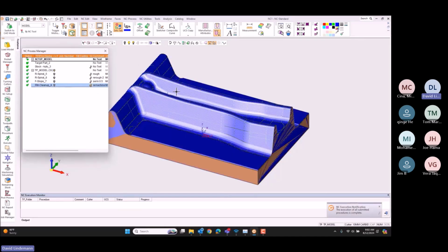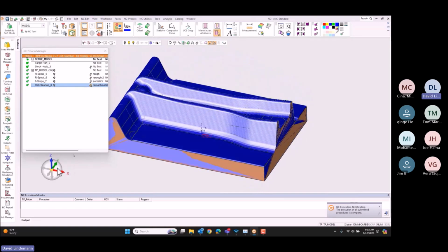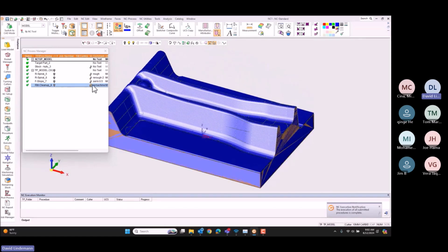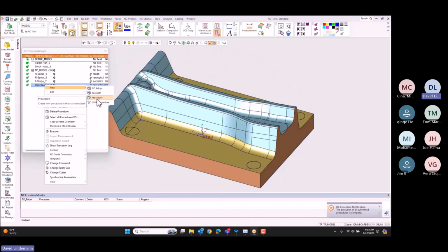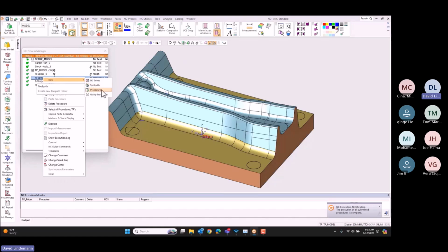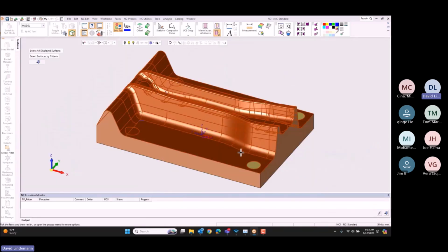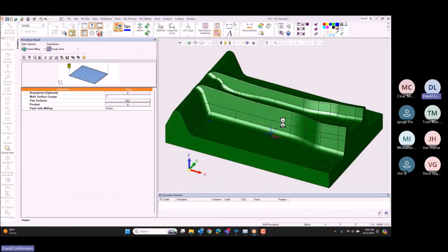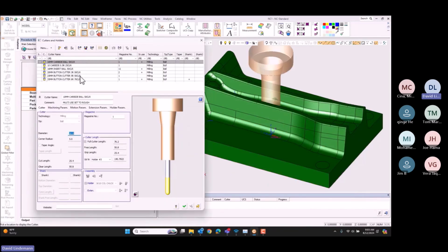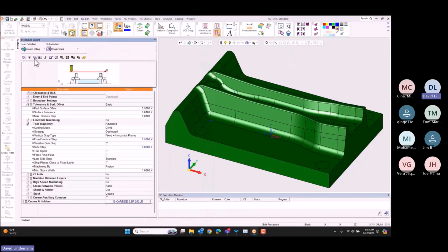And there you can see that nice cutter just targeting the corner where there's material. And the stock, you can see it's starting to look even. There's stock on that flat floor. You can see it there standing up a bit. So let's say we're going to add a new procedure to just get that flat floor, but I'm going to stick it in first. I wanted to get that first before I did the sidewalls, let's say. All right, so with that, I'll use the same routines that I've used before, but instead, let's try to use a flat cutter. That would make a lot more sense, wouldn't it? So you see in my tool, my shank, my holder, all that gets fully gouge checked. And we want to change it just to planes only.